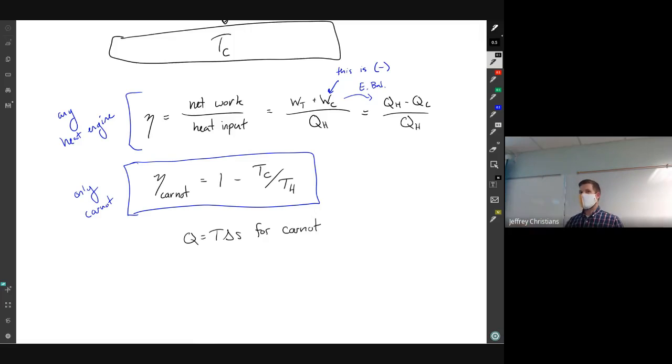If you think of our power plant in Holland, where do we dump heat? We dump it at outside temperatures. That's our low temp. If you made a power plant in Siberia versus Phoenix, the one in Siberia is going to be better because it has a lower cold temperature. All things being equal, that's going to be a better power plant.